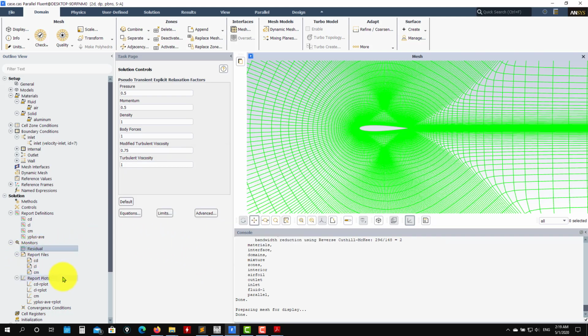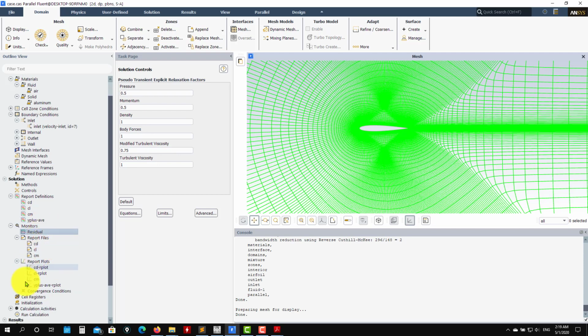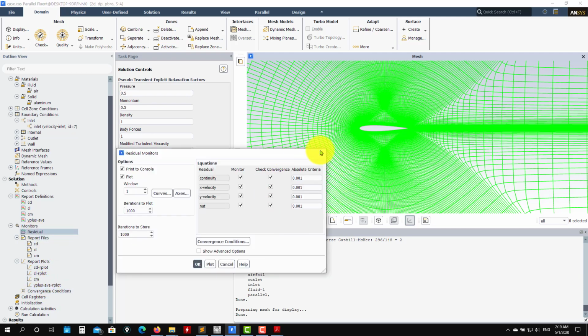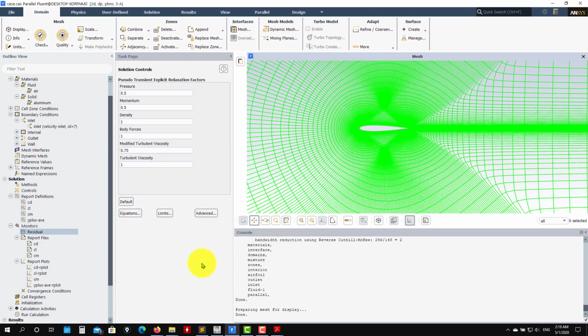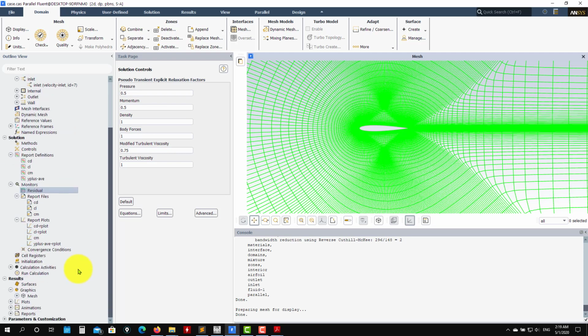You have everything here, and now let's move on to this new condition. So here we have the convergence conditions, okay? Remember that your solver will iterate, and if it reaches this condition, it will stop. Sometimes a problem will reach it really fast, but your coefficients will still oscillate. So it can be a good idea to also add a convergence condition to these quantities that you are monitoring here.